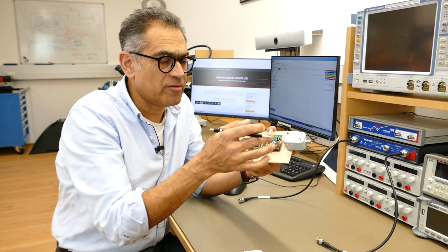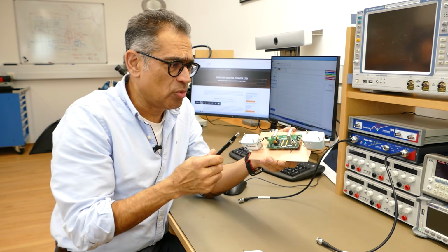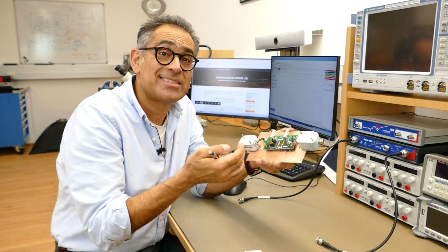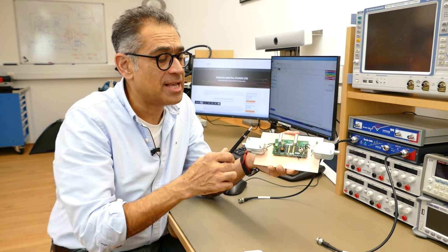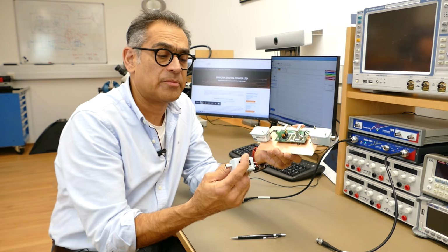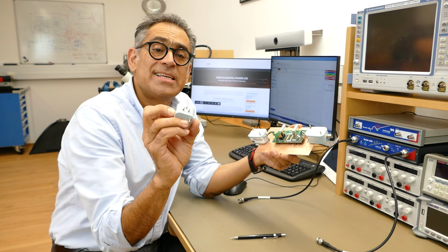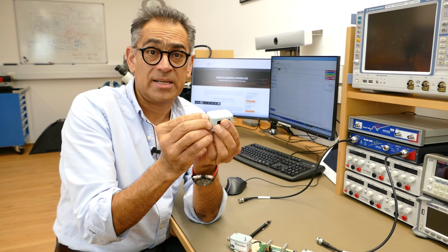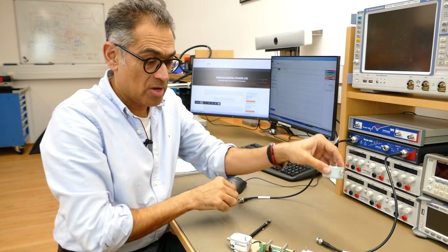Okay, so here I've got a test set up. As I described on the board, I need some one-to-one transformers in order to isolate the signal so that I can measure the differential mode insertion loss. And these are the two baluns that I have connected to my filter. You can see that on the primary side of the balun I've just got one BNC connector, but on the secondary I have got access to the center tap, which is what I described on the board.